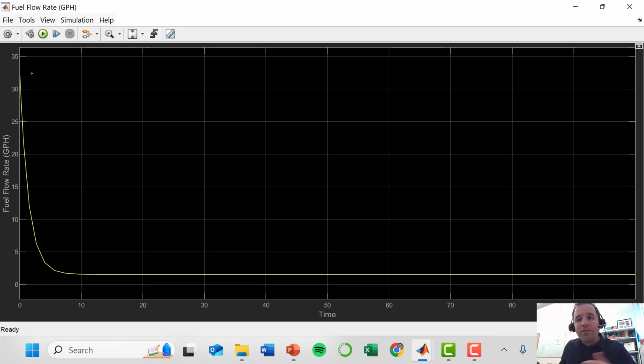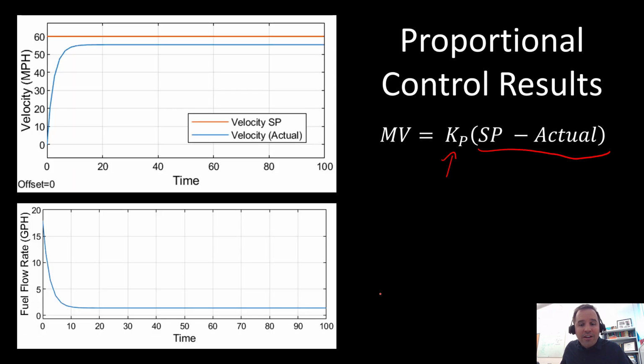So there's this trade-off between how close you want to get to your set point with a very aggressive controller gain, and then the impacts that might have on your car. This may introduce safety issues, or really, just practically speaking, just would push the car beyond its physical abilities. So the way that this is handled in control is by adding different types of controller action.